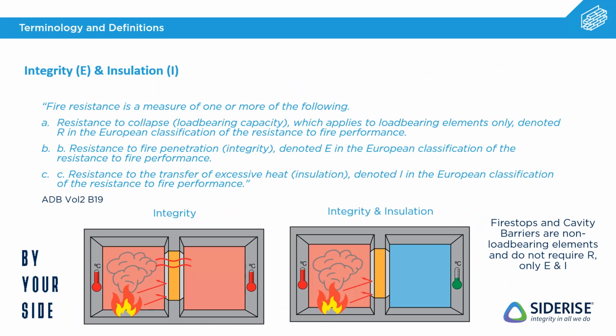Now, going on to fire resistance as opposed to reaction to fire, fire resistance is then measured by three key criteria. First of all, you've got the resistance to collapse or load-bearing capacity, which is denoted by the letter R, and that's specifically for anything that is a structural element or a load-bearing element. So things like your floor slabs, your columns, your roof, that would be obviously a load-bearing element.